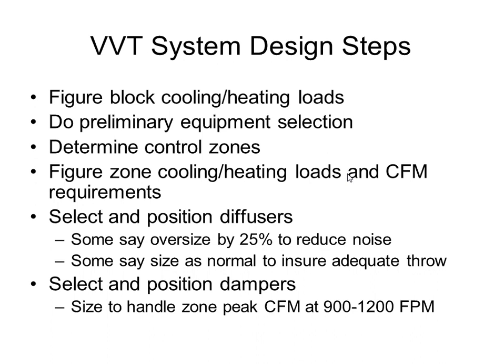So once you have your loads, you want to start going through your general equipment selection, what options you have, if you can do multiple rooftops, if you have to do one air handler, if you have to do unit vents, any type of options you can provide for the system you want to look at. And then through that, you decide, hey, maybe I can do 2 different rooftop units with zoning, or maybe I can do 3.